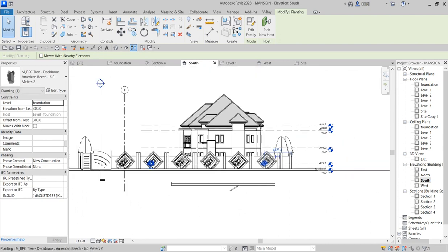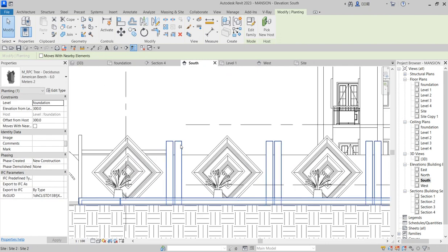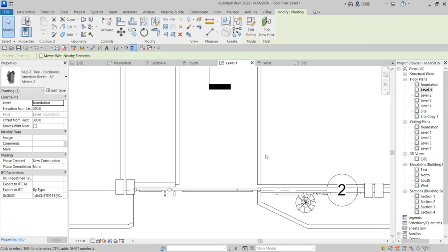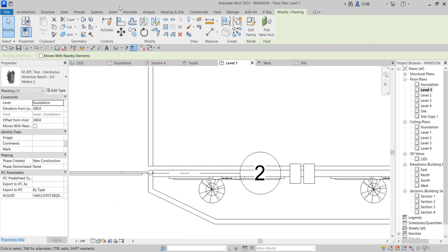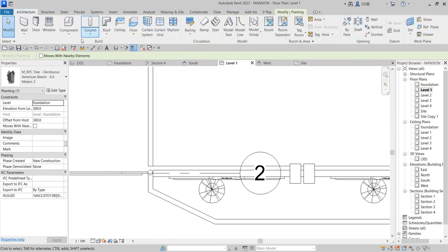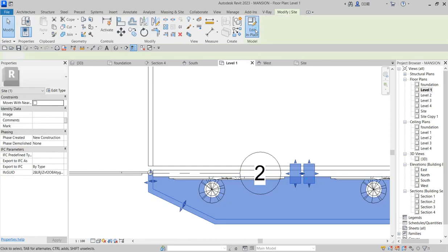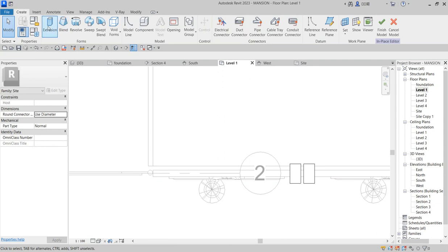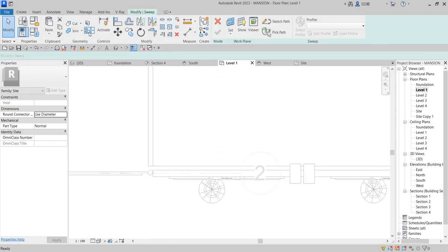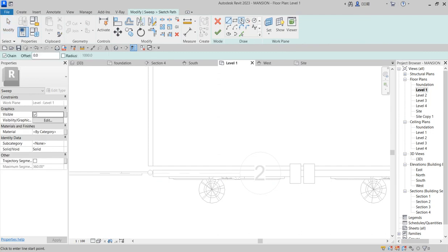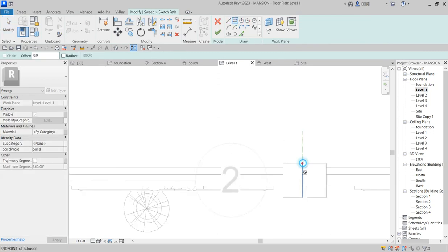So I think you're done with that. The next detail is to create the coping around this. So you go to this place, select and say use their family member, edit. So you go to your sweep, at the sweep select, draw around this.